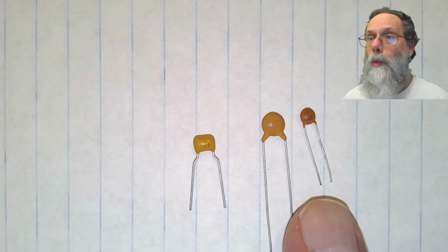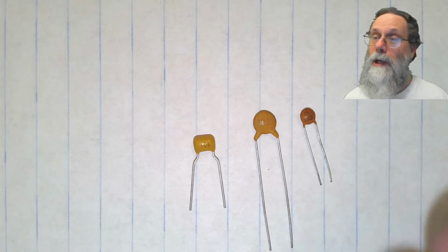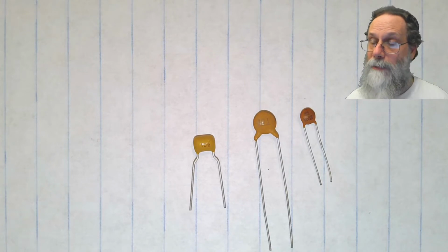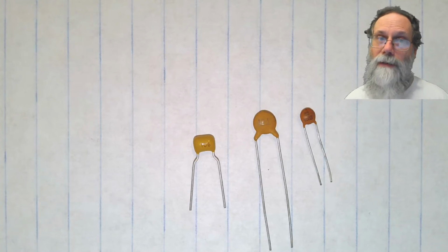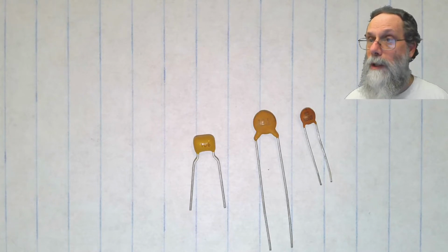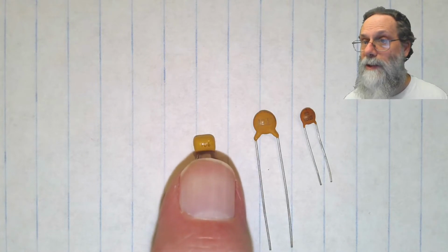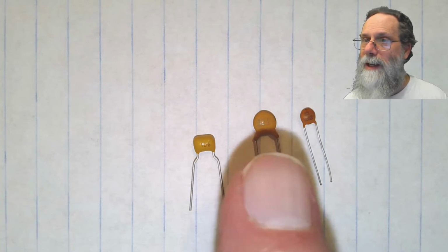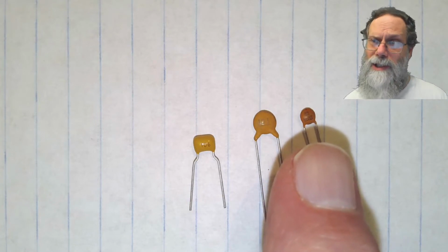Okay, what do we have marked on the capacitor? What can we tell about the capacitor? Generally, the thing we're most interested in is how much capacitance does the capacitor have. And because these things are so small, there isn't a lot of room for putting a lot of text on it. So there's a standard convention that's used for marking capacitors, and that is to put 3 digits on the capacitor. You can see this one's got a 106, hard to see, but this next one has got a 103, and this final one here, really hard to see, it's only got 2 digits, a 68.